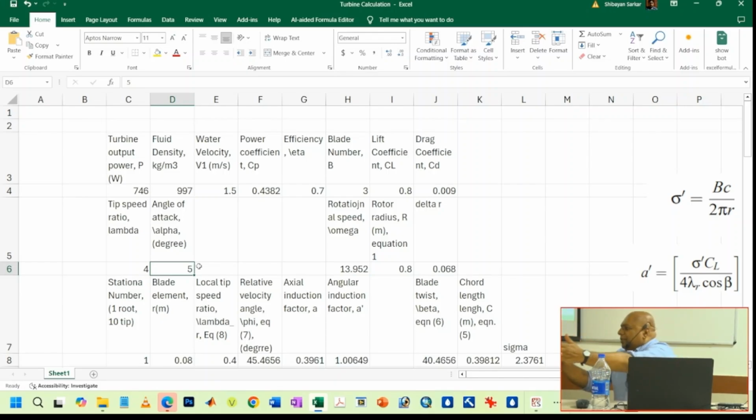But the problem is flow is coming and the blade starts to rotate, where you need to take into account relative velocity. Is that clear? So blade is here, flow is coming here, fine. But then if your blade starts to move like this, then you have to consider relative velocity, and your angle of attack is no longer fixed. You need to twist like this handle to get the maximum uniform power output.